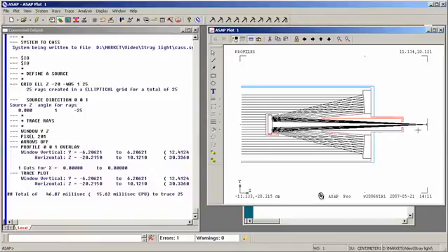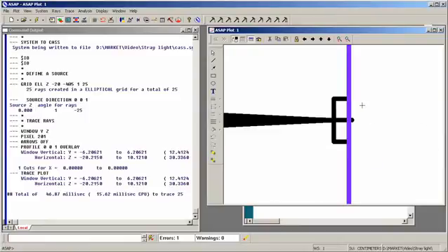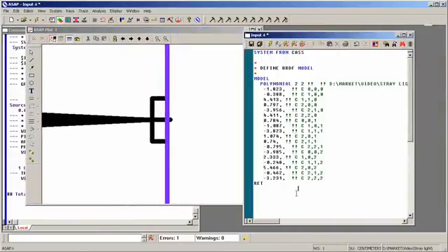Here's the geometry we had before. We want to scatter rays from the interior of the inner conical baffle to the detector. This is the detector back here. To do that, we have to define an edge. This edge is going to be entered here.